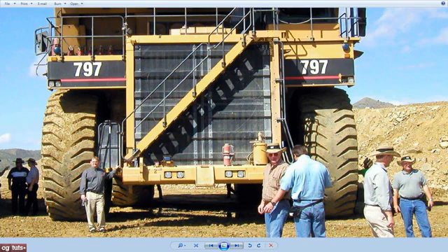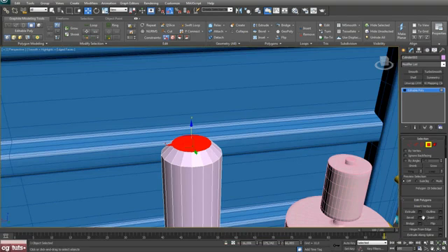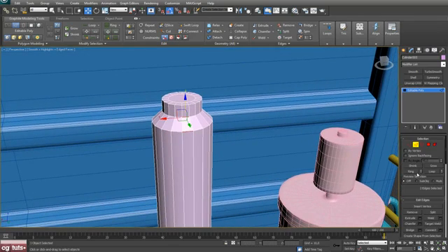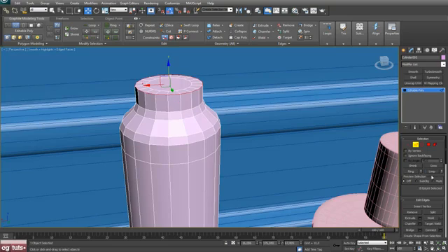And now hit extrude. 1 will be okay. And hit inset. 0.5 will be okay. Now select these 2 edges, hit loop and chamfer them. 0.2 will be okay, and with Swift Loop make 1 loop here. And also select this, hit loop and chamfer. 0.1 now. Okay.